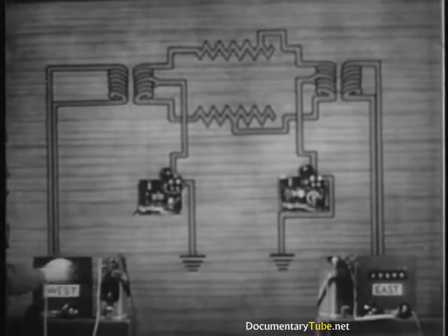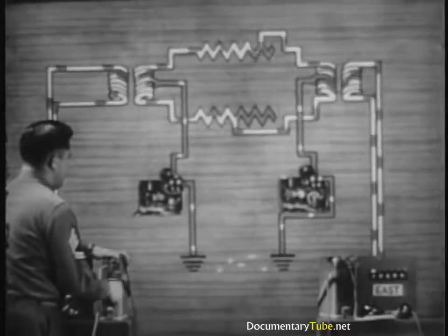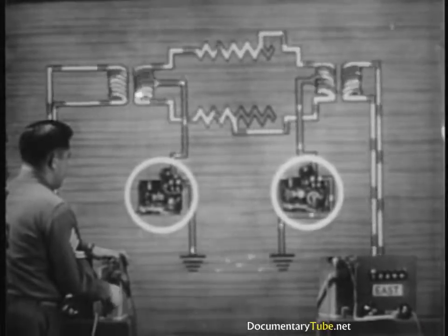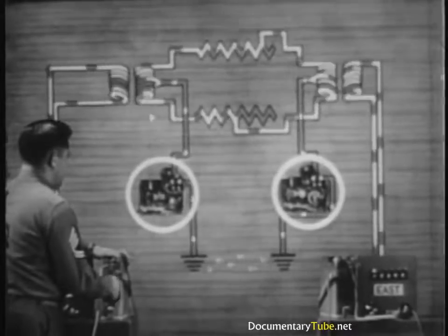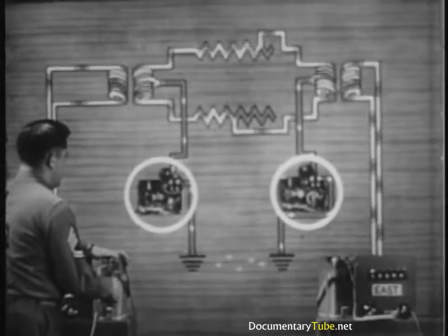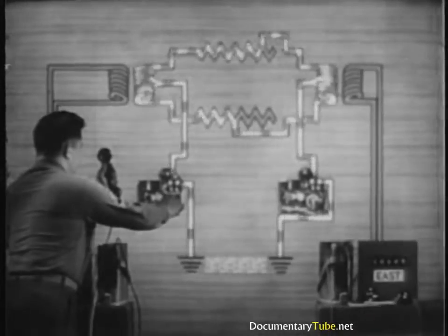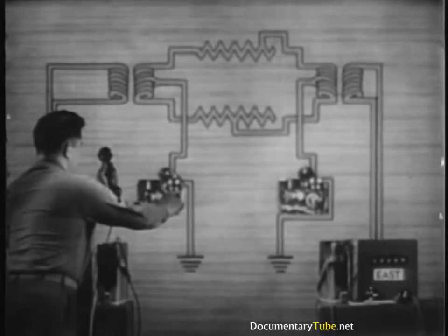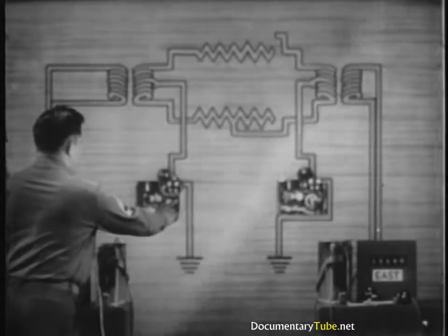When the resistances of the two line wires become unbalanced, telephone current flows through the telegraph sets, but it's rarely strong enough to interfere with telegraph communication. The telegraph does interfere with the telephone, but not sufficiently to disrupt telephone communication.